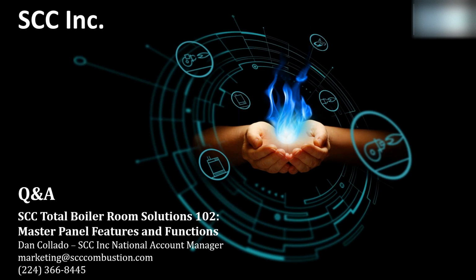Yeah, thanks, Alan. No, the master panel comes only as a complete UL listed panel. The majority of master panel applications are new installations or they're replacing installations of existing lead lag panels, and they're going to be mounted separately on the wall. As a result, the only option for the master panels are complete enclosures. We have NEMA 1, NEMA 4X, or NEMA 12 as an option, and you can actually add cooling fans to any of those options as well.